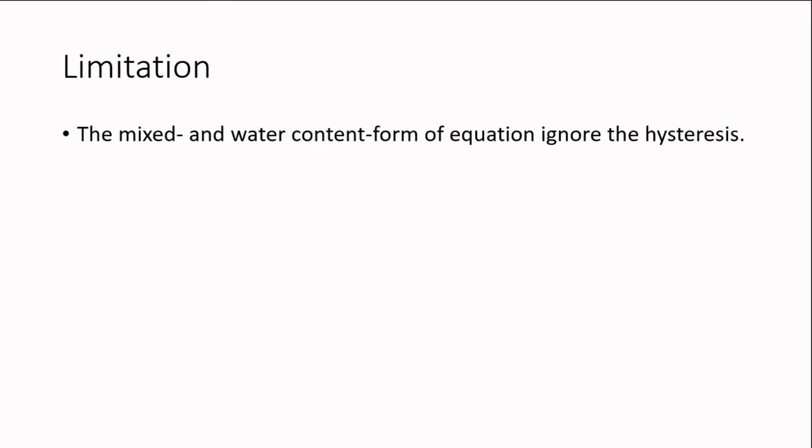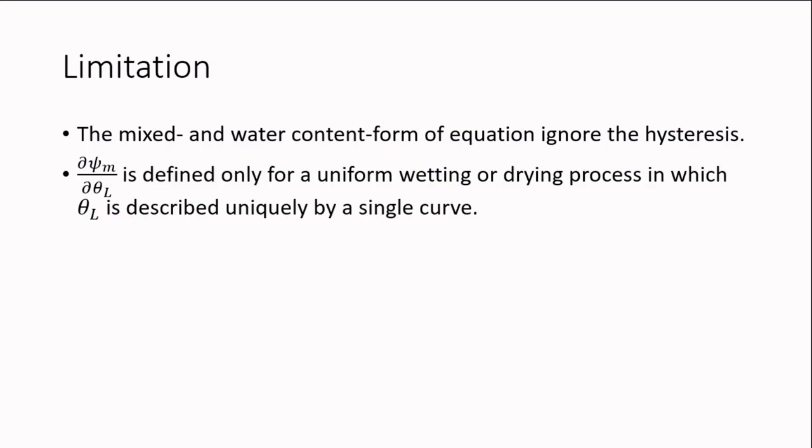Okay, there are also some limitations with the Richards equation. The mixed and water content form of the equation ignore hysteresis. Hysteresis, remember the one that we talked about in the previous chapter, the wetting and drying water characteristic curves, they are not the same. So this equation does not take that into account.